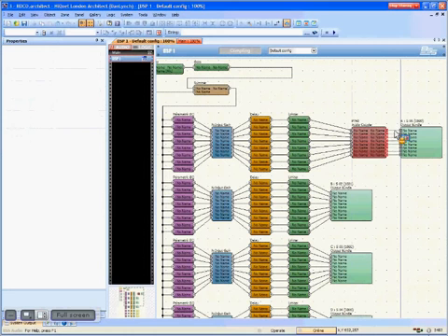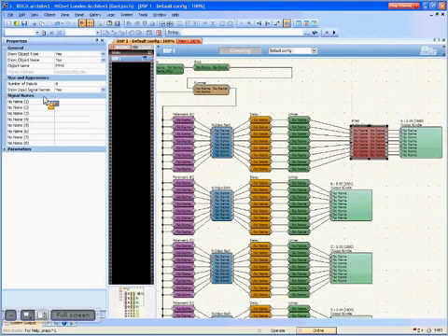What the audio coupler does, if I can get it wired up right, there we go. Over here under properties for the audio coupler, we can change the signal name of each thing that goes through it. The audio coupler does not do anything to the actual signal, it just changes the signal name as it goes through. So this might be zone 1, this might be zone 2. The names are changing there on the screen as I type these in. So now our outputs are actually named. Wherever this bundle goes, it'll take those names along with it. That's the audio coupler. Cool piece of gear.